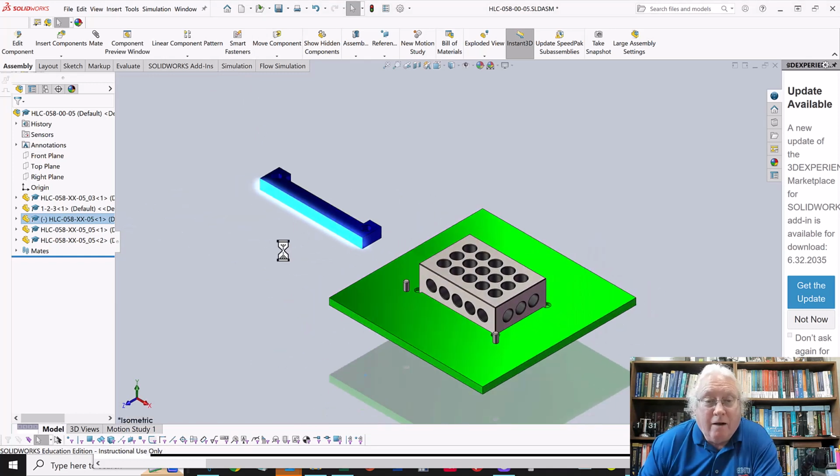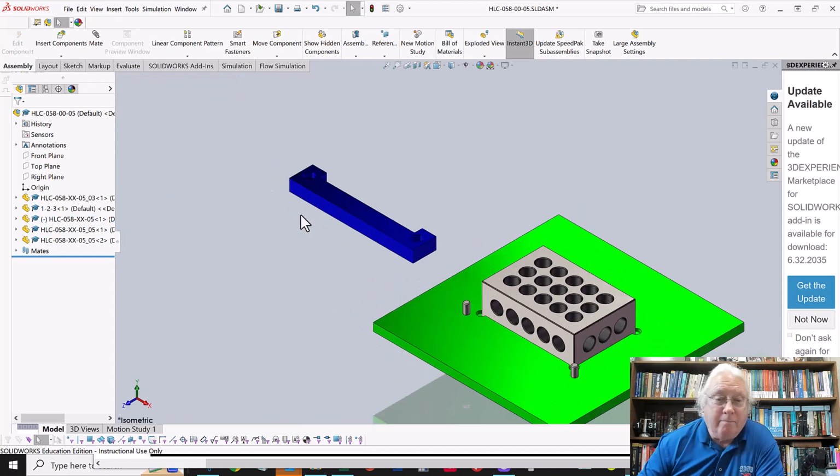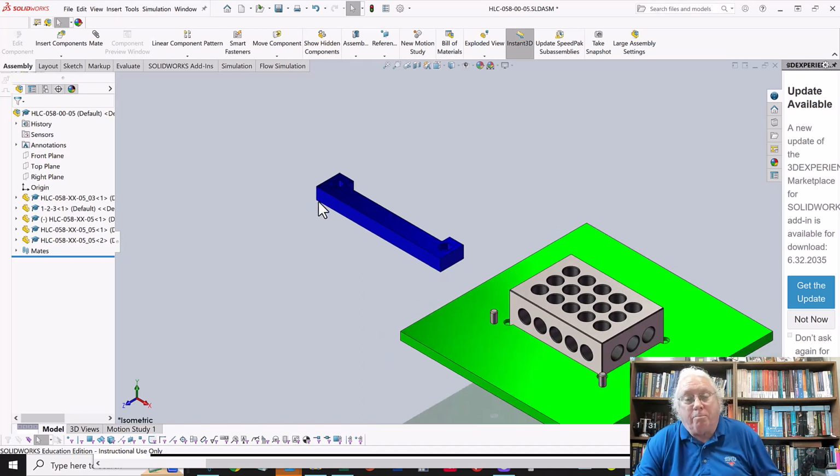And now what I'm going to do is create my datum reference plane for the part. And so this scheme is what you're going to use for assignment 5, as opposed to the scheme we used on the first assignment, or the first video, excuse me. So what you're going to want to do is determine what is your primary datum. And the primary datum is the bottom of this part. I want that to define the primary datum because that's the way this part is installed. That's the design intent, is this part's going to be installed on a plate, and that's the first plate it mounts to.